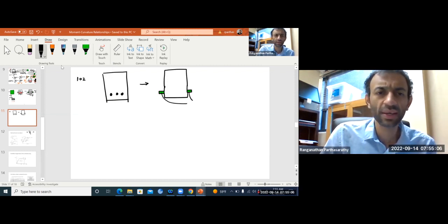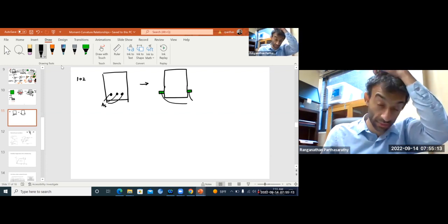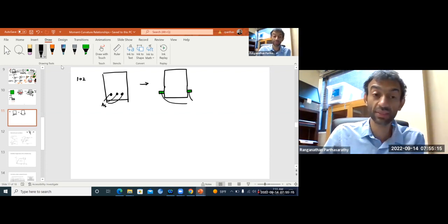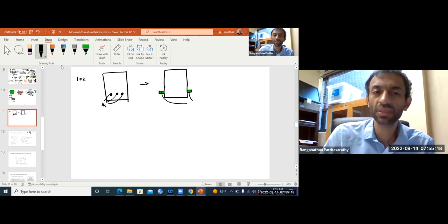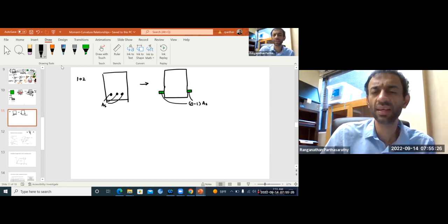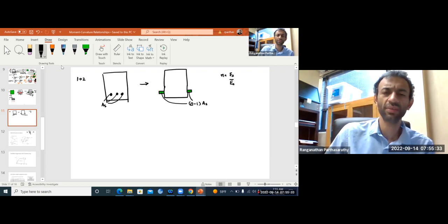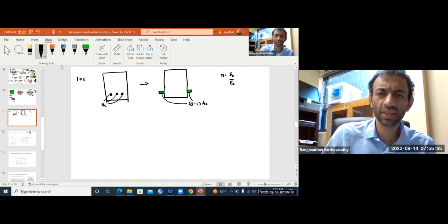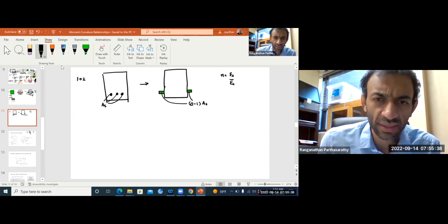should be here. Your area of steel, area of all the bars together, is AS, area of tension steel. If it is compression steel, you will put a prime. So here you will change that to (n-1) AS. What is n? Remember, n is the modular ratio, modulus of steel by modulus of concrete. Why -1? Because like this.